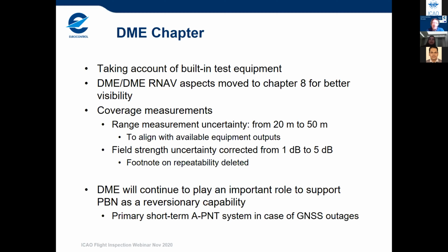So one was the range measurement uncertainty, and that is often actually limited by the available equipment output of DME interrogators. So when they have an output with a resolution of 0.1 nautical miles, of course, you don't get down to 20 meters.